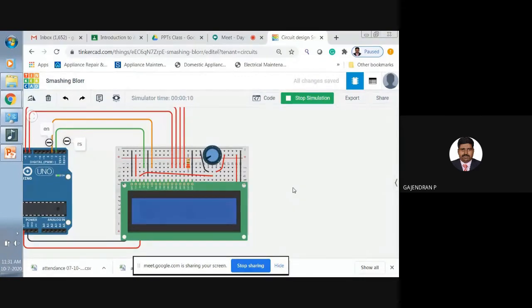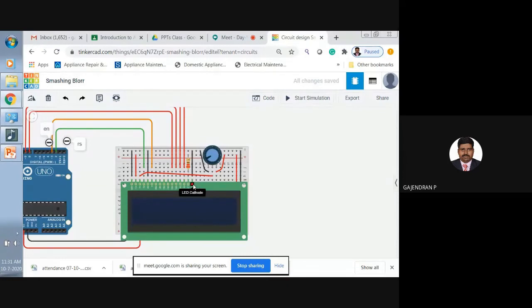These things you can write in any conditional statement also. You can write that whenever I press a push button, my LCD display has to turn on. Likewise, you can do it. And one more thing, for this power pin also, the backlight you can control using your program. Because for the backlight, again, we are going to use a 5 volt DC supply only. Instead of connecting straight away to the VCC terminal, I can connect it to any one digital pin and turn the backlight on.